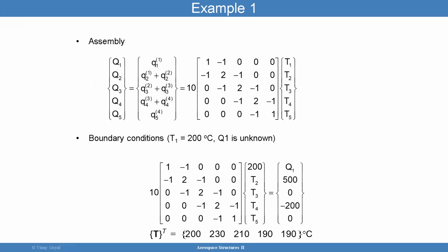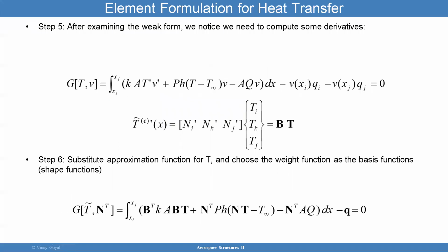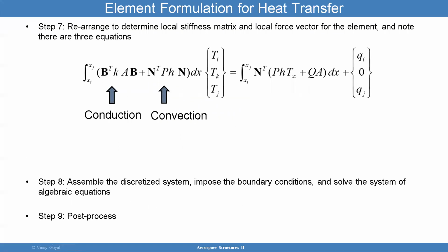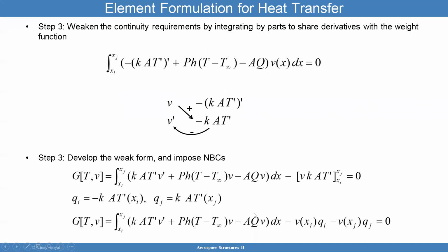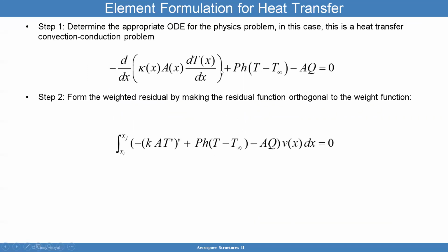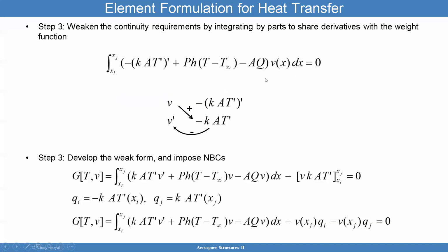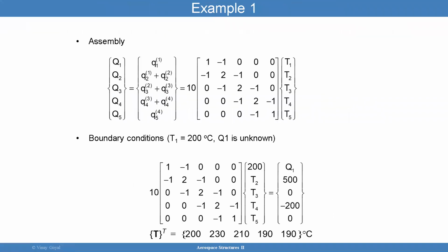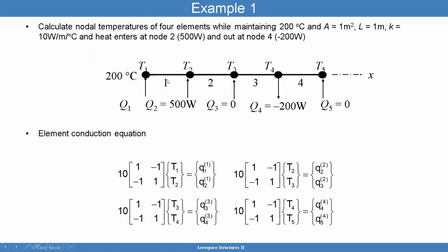So look at how we took this problem, this differential equation, and solved for temperature using linear algebra, right? We solved it just using this. And how do I know what the temperature distribution is across the element? Well, I told you that I know there's a polynomial approximation across it. So if I know T1 and T2, then I can determine what the distribution of temperature is across these two elements, two nodes.